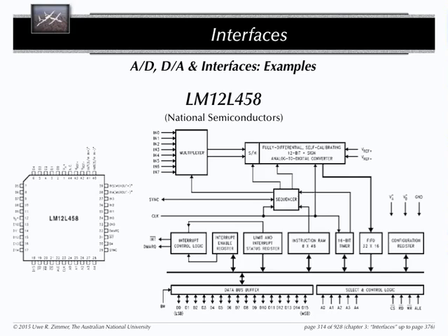Interrupt registers, telling this thing what kind of events is supposed to trigger an interrupt. There's also an interrupt output from the interrupt control logic in that chip. This interrupt output is, of course, also to be wired somewhere in your CPU. Usually goes into your interrupt controller. But this device has only one single interrupt output line, nothing else.